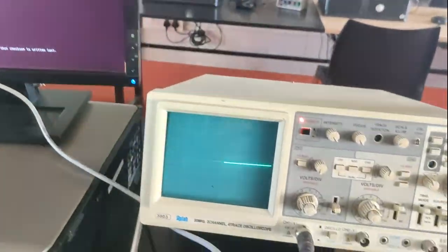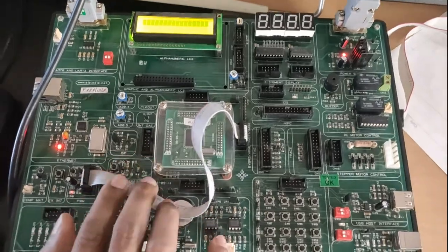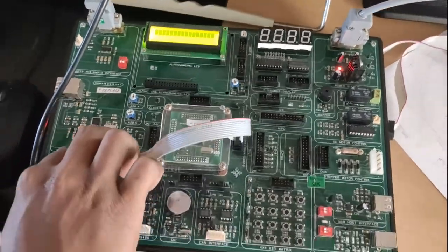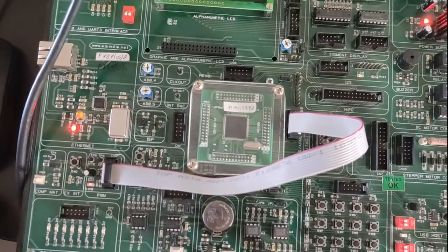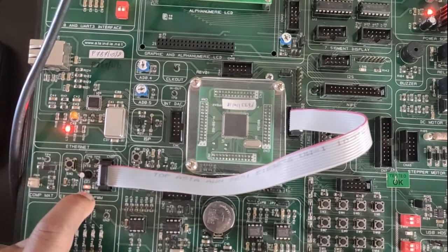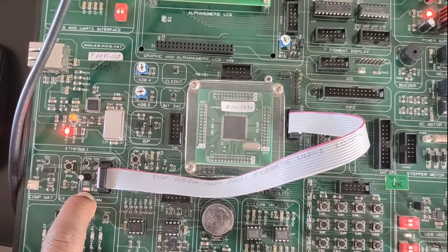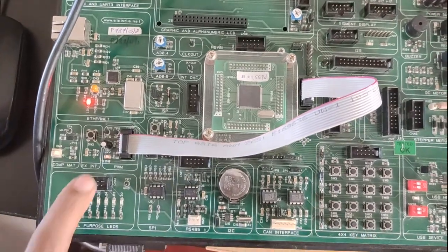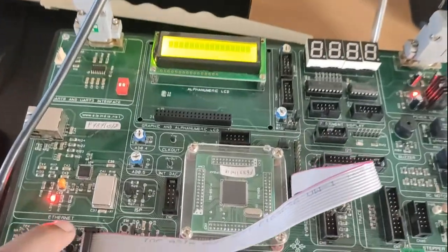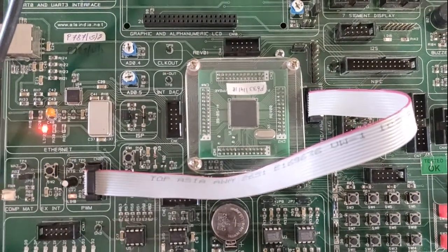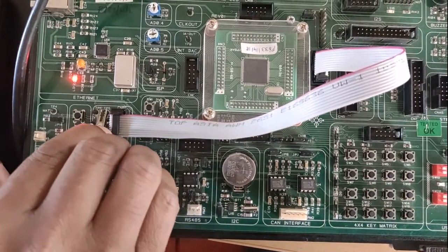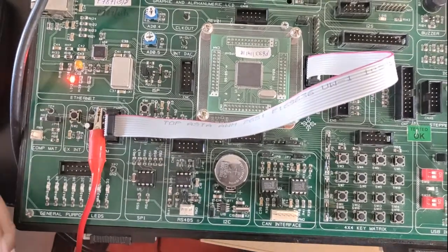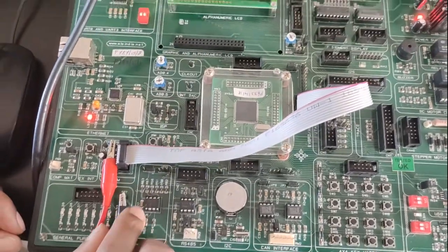Now reset your code. Before resetting, make sure the proper connections have been made. The internal PWM pins are available on the C and B connectors. Here LED10 is used to show the intensity variation of the pulse width signal. In the PWM signal you can observe two outputs, namely voltage and the pulse width signal. Now I'll connect the probe positive to the output, that is TP5, and the other end to the ground.